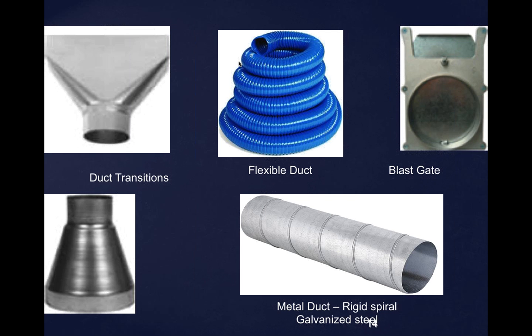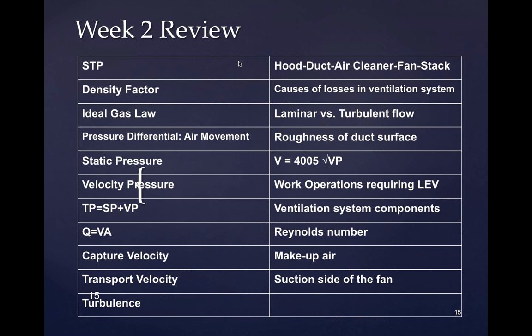I think if you look at some of the PowerPoints, particularly the Jeff Burton PowerPoints, he has a couple of situations where he shows where you might get downdrafts. Remember, he doesn't like rain caps at all. Did you catch that in his presentation? Hates rain caps. I don't know what he does about the rain, because without a rain cap, it's raining in and you're getting water inside the exhaust duct when it's not running and stuff like that. But he doesn't like them because, number one, they interfere with the flow of air coming out of the exhaust system, so they're one more source of loss of energy. And number two, they direct the exhaust downwards. So if it's particulate, you're just turning it around and dropping it down onto the roof.